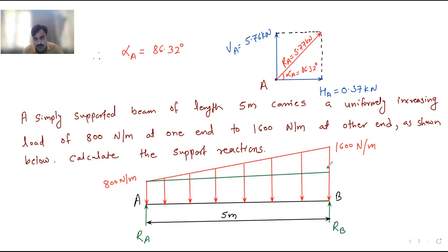So this is the perpendicular, exactly a straight line. Now you can see that this load at the bottom has become a rectangular load. Rectangular load means UDL. And the triangular load above is the uniformly varying load, the UVL.